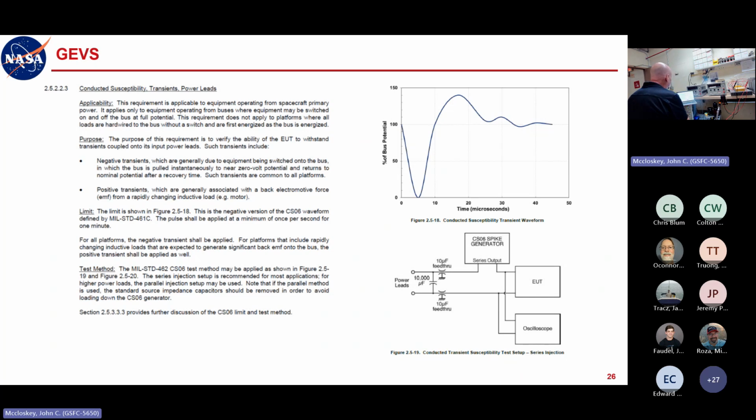where CS106 came and went with one version of the MIL-STD, at least for a time, you had to buy a dedicated signal generator to get that 5 microsecond pulse. I mean, you see that these are kind of unique pulses. I shouldn't say they're terribly unique, but you generally buy a dedicated signal generator to give you that pulse shape, right? And for a time,